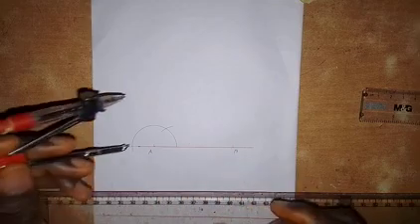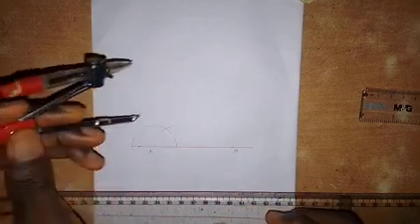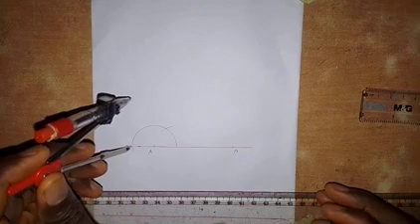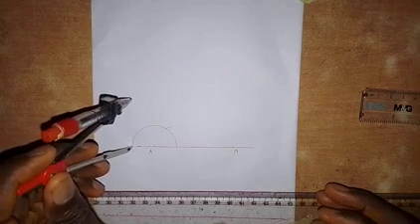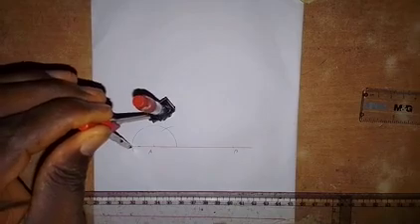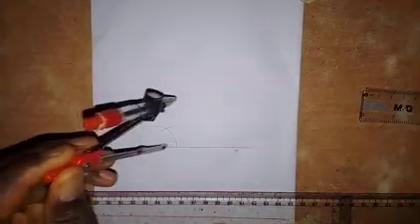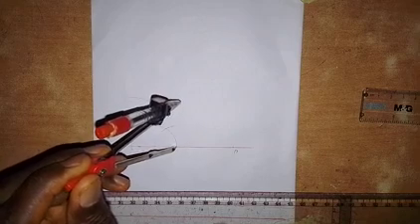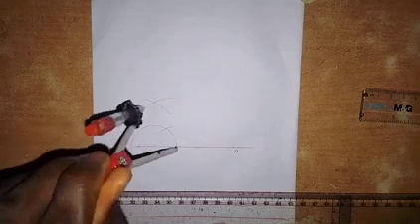So now we need to add 15 degree to this 60 degree to make it 75 degree, and to do that, we need to divide this semicircle, which is 180, into two equal parts so that we can have 90 on this side and 90 here, and then we'll be able to add 15 degree to this 60. So how do we do that? Put the pinpoint of the compass at this point here, and then extend the pen point to a convenient radius. You draw an arc here, and then put it at this point here. Okay, put it at this point, then you draw an arc.